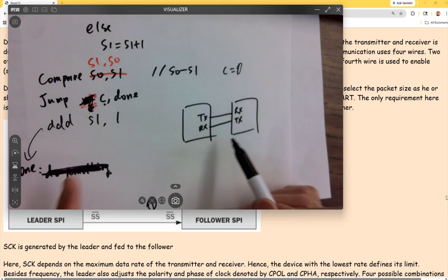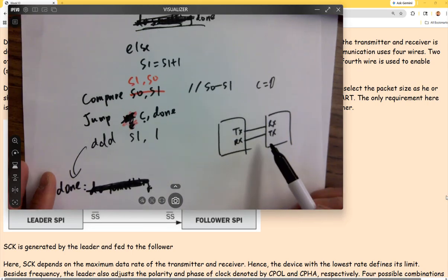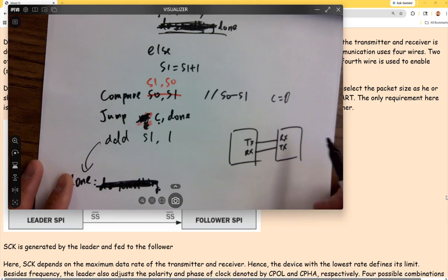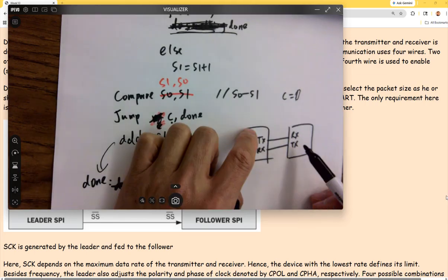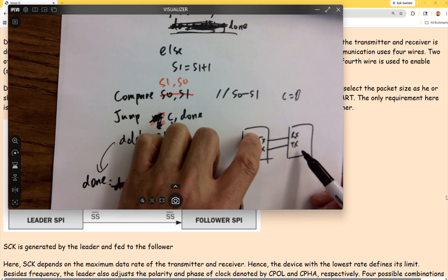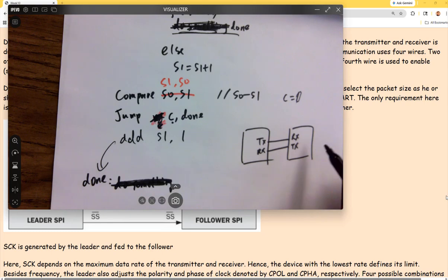Okay, and there isn't a common clock to synchronize both devices, which means even though you are trying to synchronize it, your rising edges to falling edges could have time delays. So you won't be able to synchronize both transmission and receiving. So where's the clock for UART?